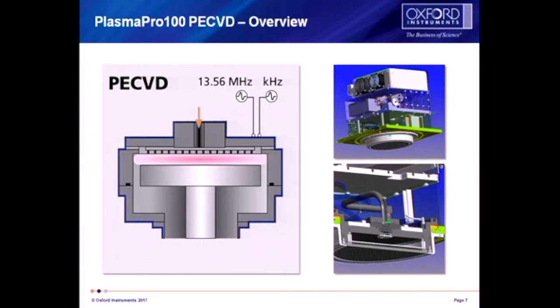So when you have a very high frequency power range, it's very good at getting the electrons to move because they're really light, but you don't get that much movement of ions because they're much heavier. So when you use a lower frequency, your ions kind of have time to catch up and can be used to bombard the surface. And when they do this, it almost packs your film down, so you end up with a much denser and much more compressive film. And by varying high frequency and low frequency pulse times, you can tune your films all the way from compressive to low stress to tensile.